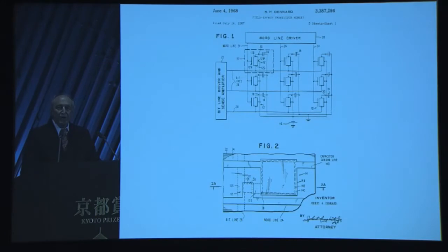One of the practical problems we had to face was how to design MOS transistors with such very small dimensions. We knew that just reducing the size caused them to switch on and off poorly. My small group responsible for the MOS transistor design considered all the problems, and it soon became clear that there was a general way to design smaller devices which involve scaling down of a few key parameters. This is illustrated in the next slide.